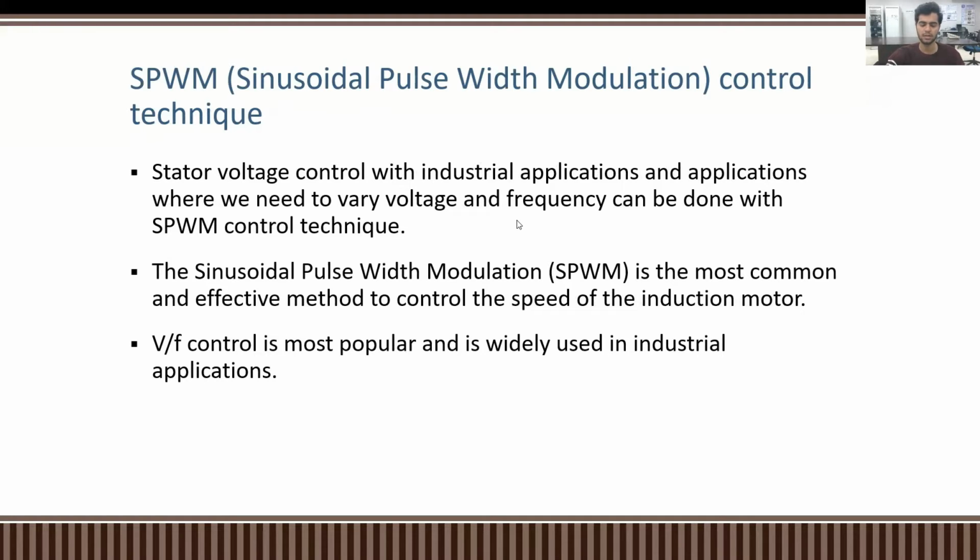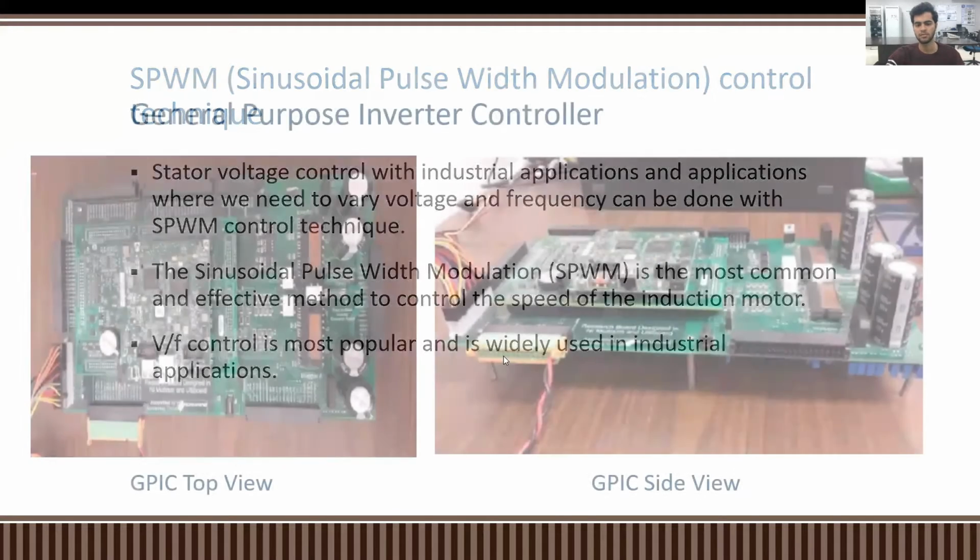They simply do as we have done here, changing voltage and frequency at the same time to control the speed of the induction motor. SPWM is a very common and effective method to control the speed of an induction motor, like the V/F method I mentioned earlier.